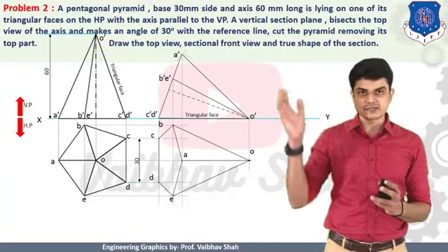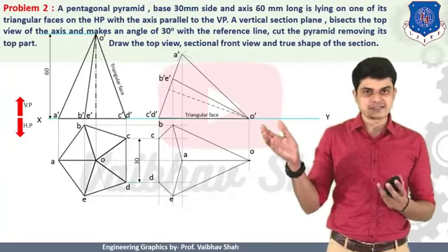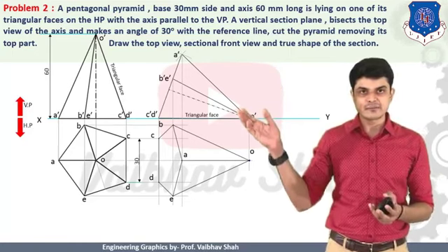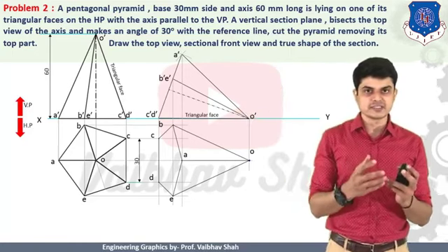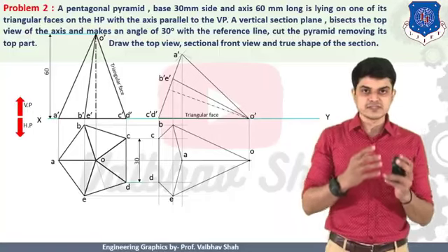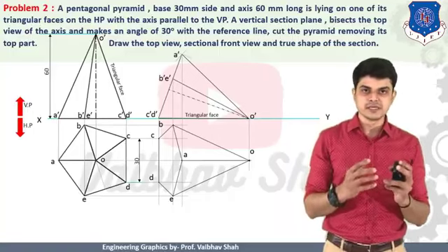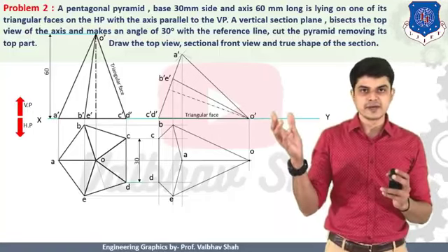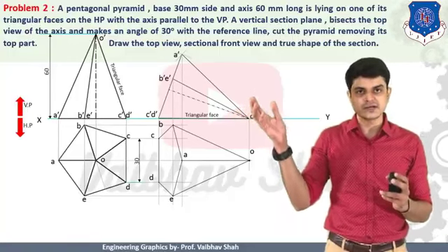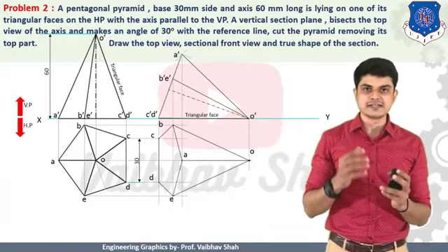When we try to take the top view, it is obvious that O dash point is clearly seen, and the base is completely seen. So each of the points of the base is completely seen, but there is one surface which is hidden from your observer, which would be your triangle face itself, O dash, C dash, T dash, because it comes under your object, so it can't be seen by taking its top view.